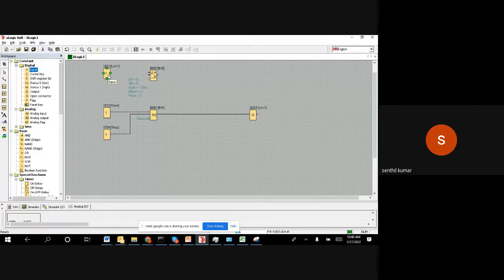Basically, what I picked up is the input under digital, and I am trying to connect the digital input to the analog comparator, and it is not connecting. So the program itself is trying to understand my problem, and it is not allowing it. It is avoiding it. So it's correct actually, because technically it's not correct. What I am supposed to do is take an analog input because it's a tank level, right? So the system is also helping me understand why it's not connecting. Now it will connect actually, right? That's a small mistake.